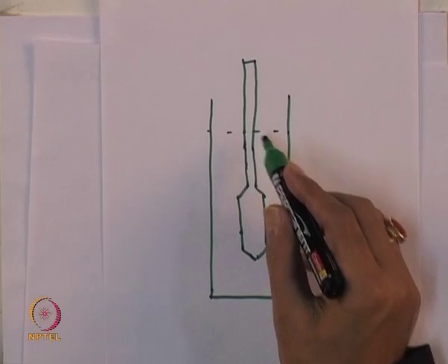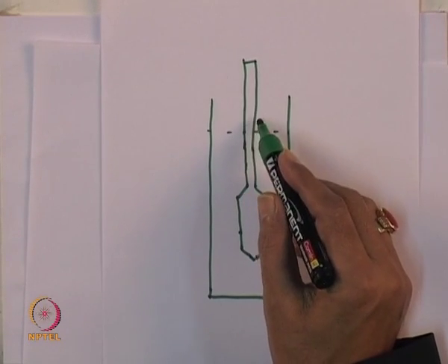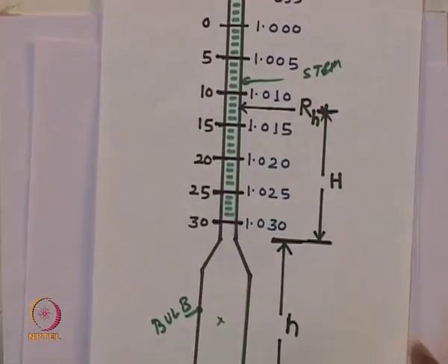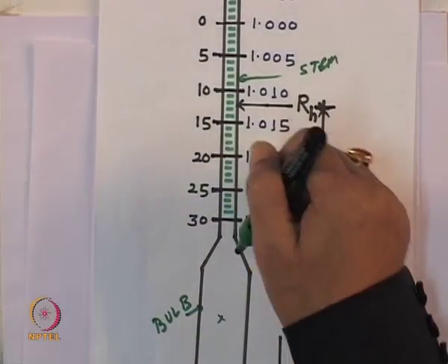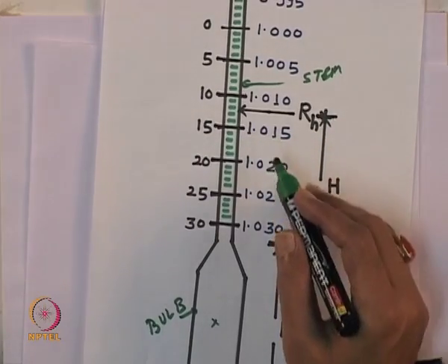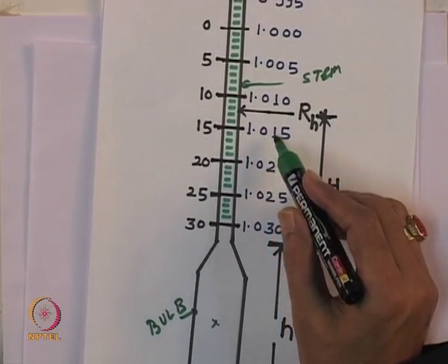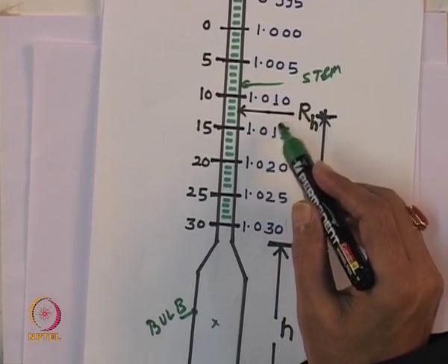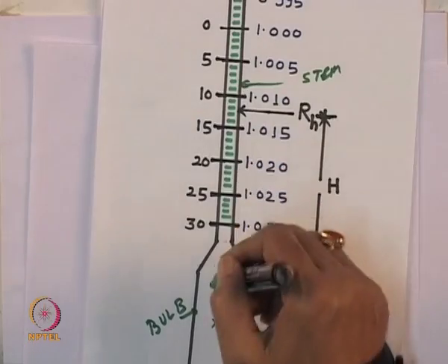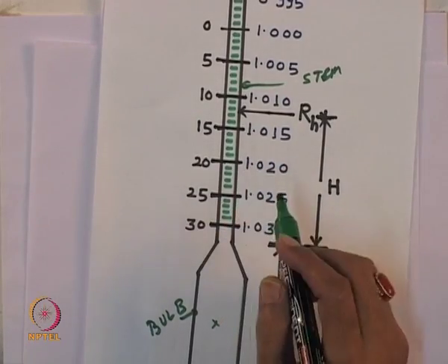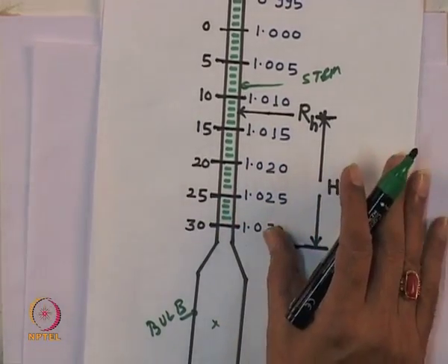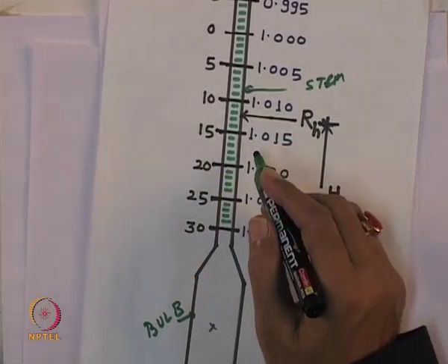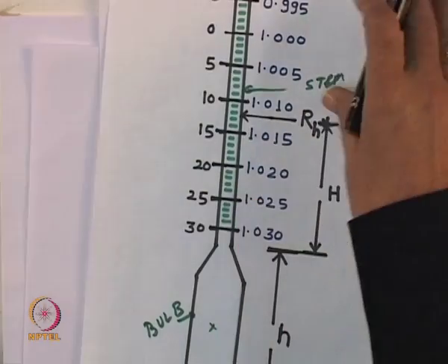You take the hydrometer reading at total elapsed times of half, 1 and 2 minutes without removing the hydrometer. After the 2 minute reading, then remove the hydrometer.